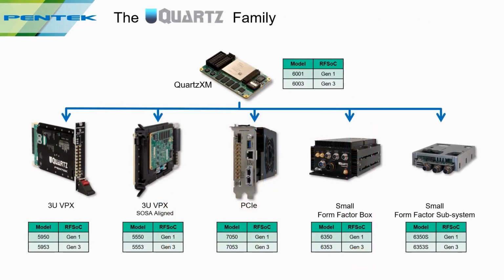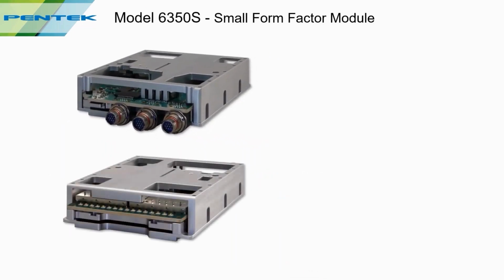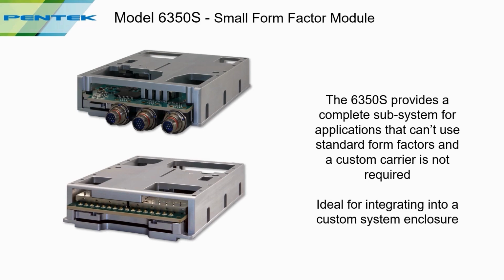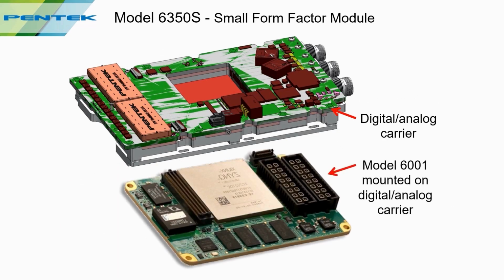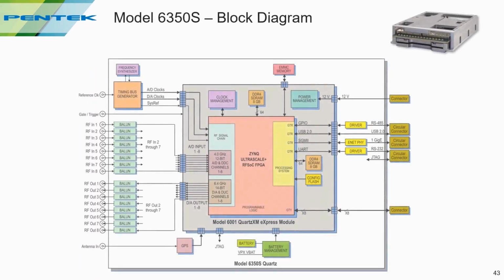The last model on this slide is a small form factor subsystem. There are certain instances where a board level product isn't appropriate and the rugged box is actually more than is needed. So this is a self-contained module designed to be integrated into larger systems. And just like our other system on module and carrier board sets, this is the same thing. In this case, this is the carrier with all the analog and digital interfaces to the outside world, and the Quartz XM plugs into this and provides a complete acquisition and a processing system all in this small package. The block diagram here looks again very similar, but with the I/O connections appropriate for the installation environment.